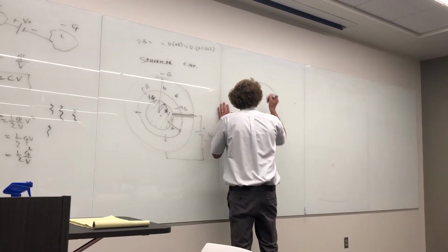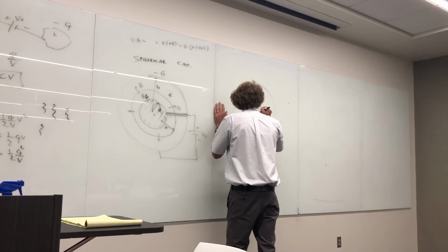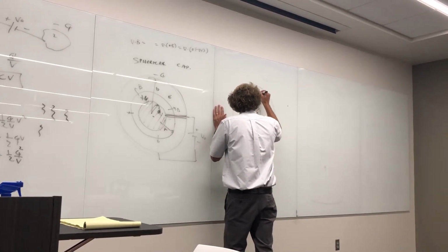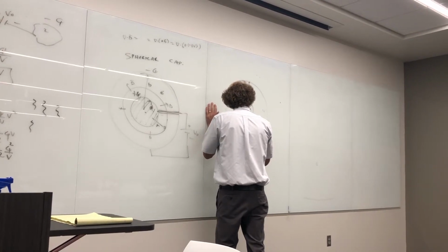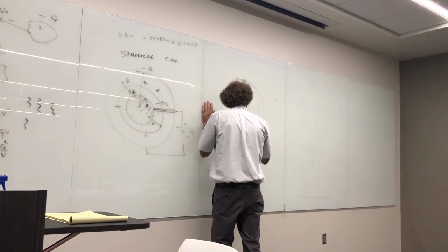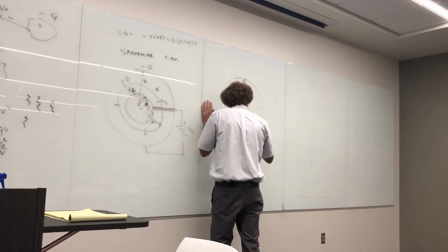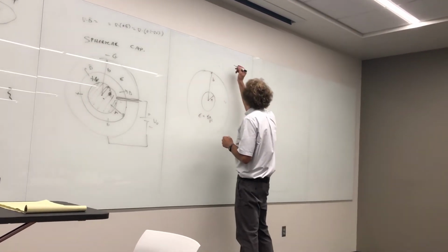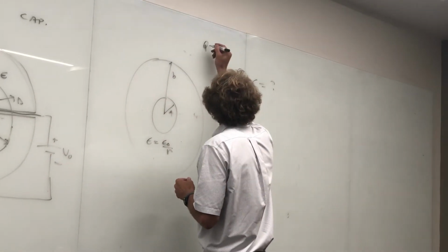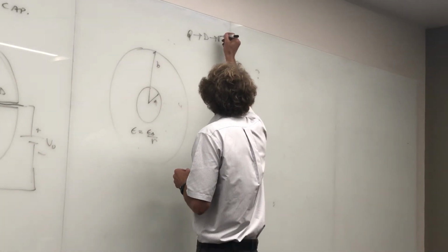Find the capacitance between the inner A and outer conductor B. This is in spherical symmetry. If epsilon is equal to epsilon naught over R, I want the capacitance. I would suggest you assume Q, get D, get E, and then get V.